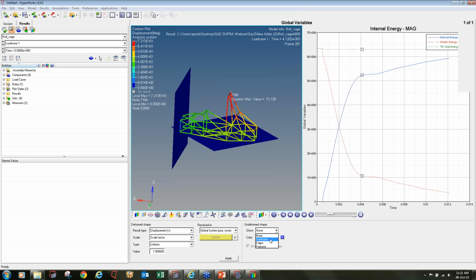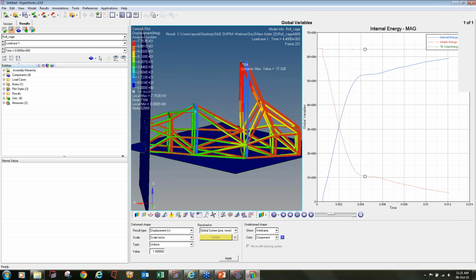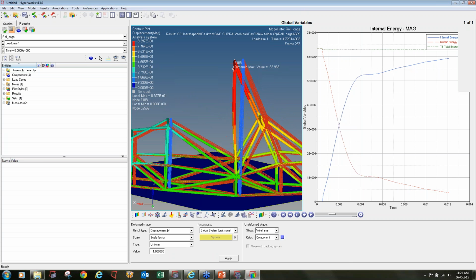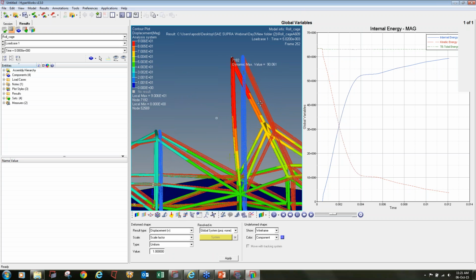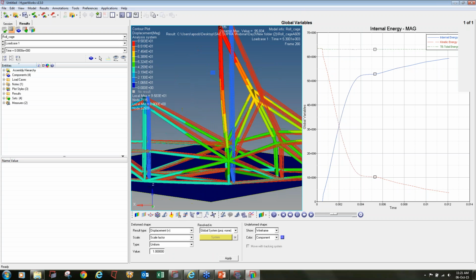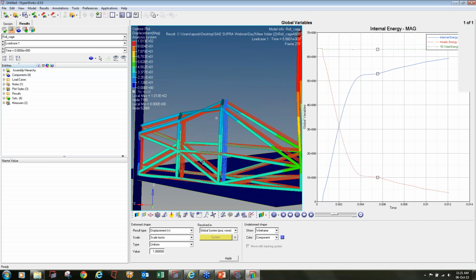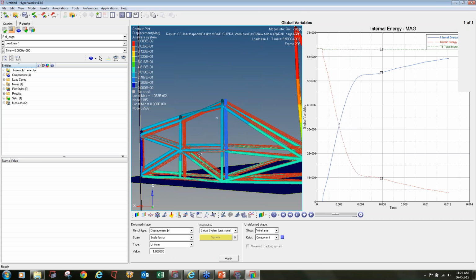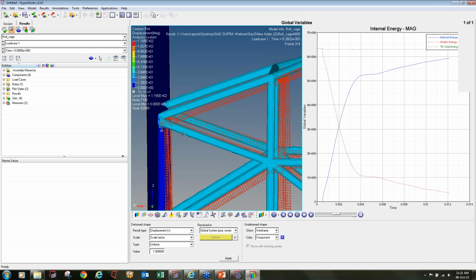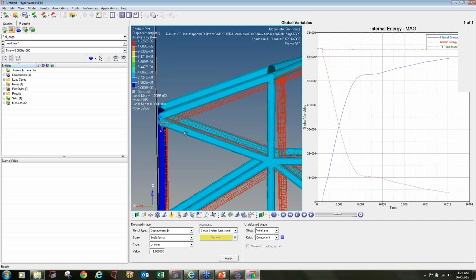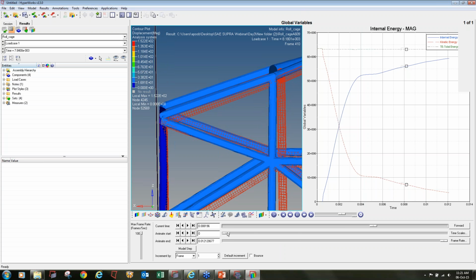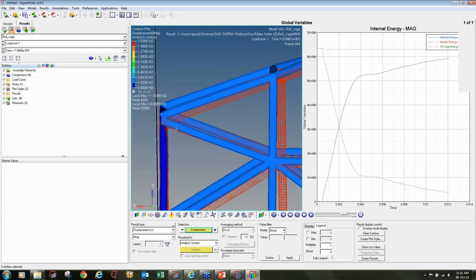You can also see the deformation. So my rear roll hoop is deforming, as you can see. The rear roll hoop, rear member is deforming due to the front impact. So you can see it has captured the bounce back effect also. So you can see here, if I put the wall parallelly, so it has impacted and it is bouncing back again.